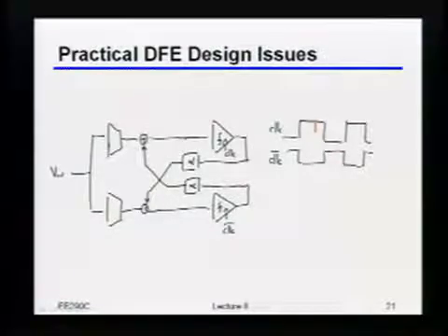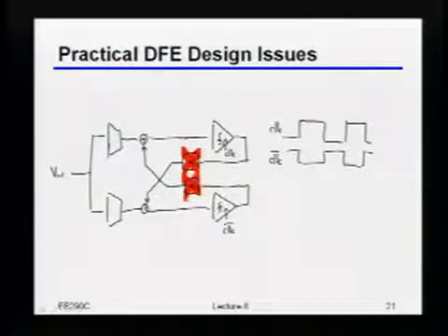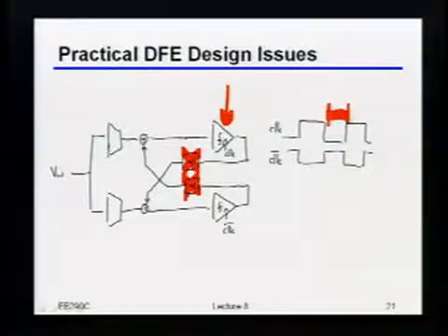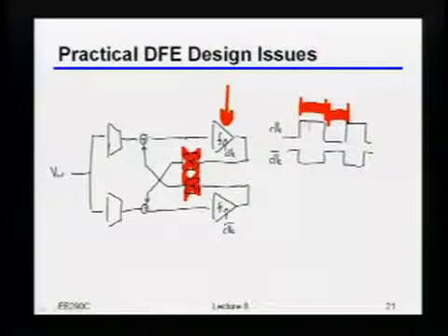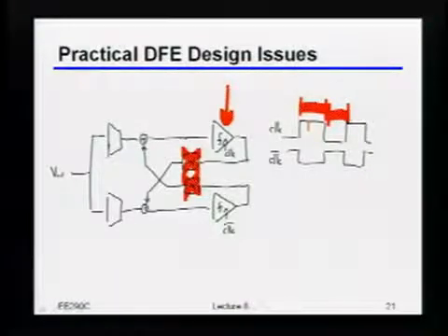Okay, so in this particular example, it turns out to not buy you anything, which is kind of why I did it this way. But imagine that I wasn't closing the first tap. If I didn't need to do this, then notice my comparator has twice as much time to reset itself. And in principle, if I was really limited by, let's say, a CML comparator or something like that, I've also got twice as much time that I'm staying in the input sampling phase. Of course, that means not closing the first tap, meaning unrolling the first.